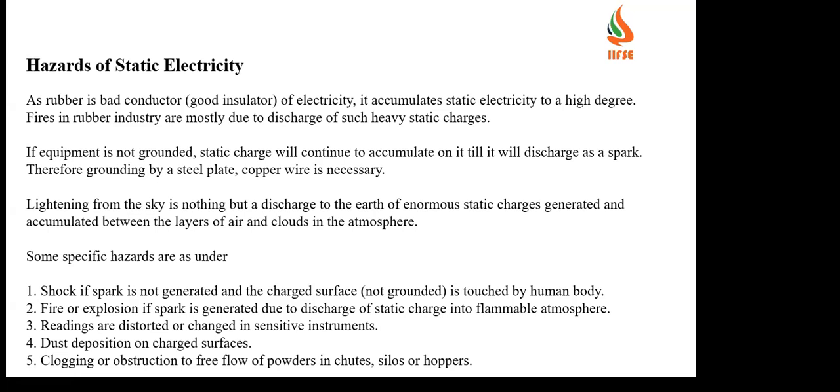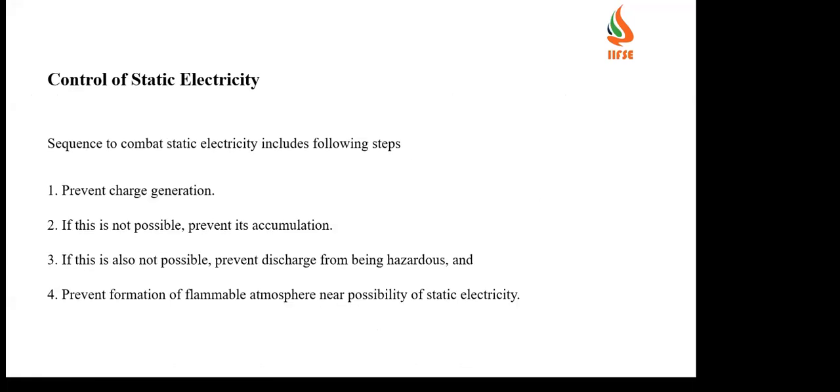Then, readings on sensitive instruments can get distorted. The readings also get damaged if the equipment is highly sensitive or sophisticated. And dust deposition on charged surfaces, and clogging or obstruction to the free flow of powders in chutes, silos and hoppers. These are some of the specific hazards of the generation of static electricity.